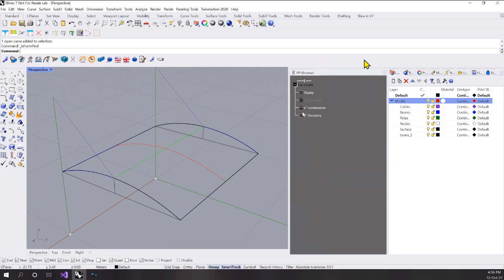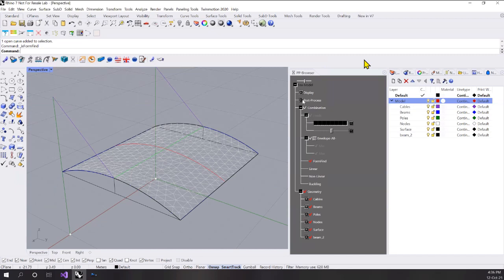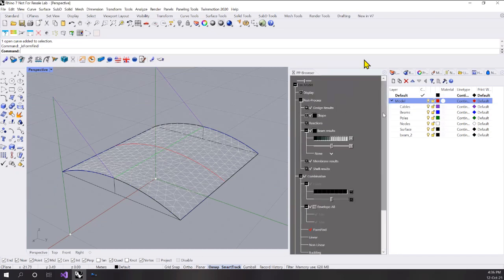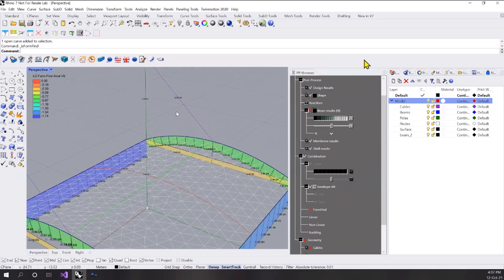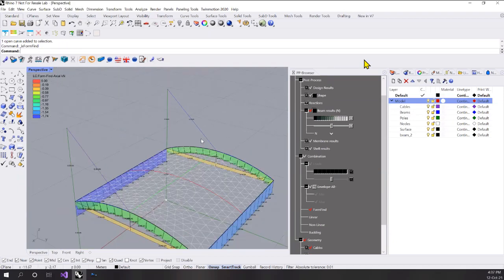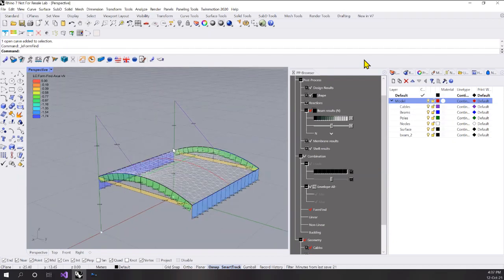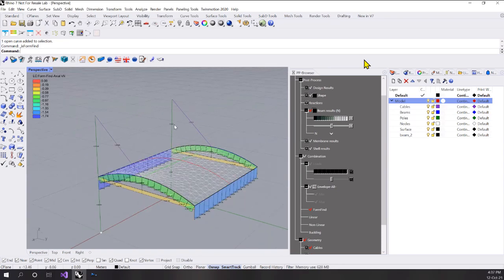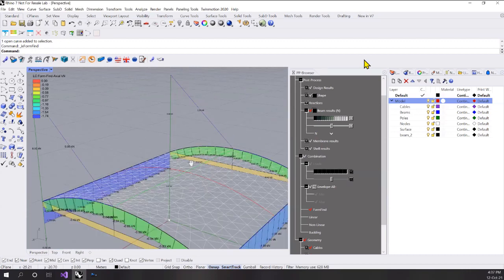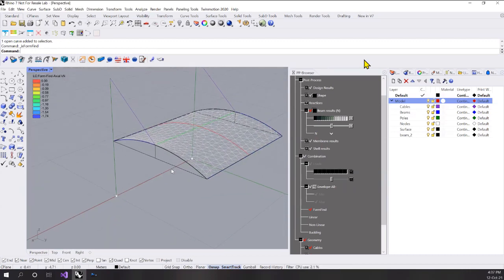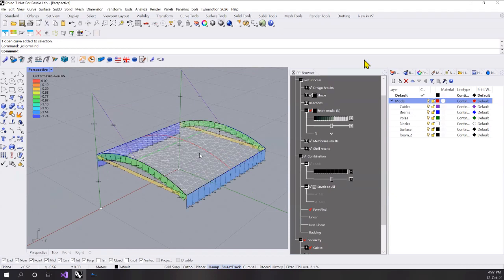Okay, so we can activate the geometry and we can activate the form finder and give a look at the forces. Yeah, now we have forces on the cables. Oh no, zero, almost nothing. I think because it's... no, there's no self weight, there's only potential. Sorry, it's true. Clearly we are running a form finding, so only the protection of the membrane is active on the model in this moment.